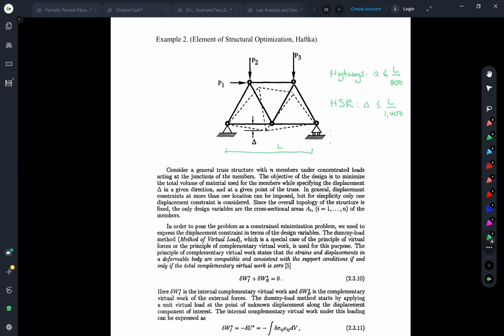It depends on the situation as well, but the deflection limit is very, very strict. I have to design my bridge to have very small deflection to guarantee the comfort of the people in the high-speed train, so you will feel nothing when you ride on the train on my bridge.